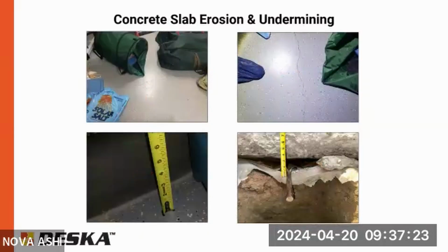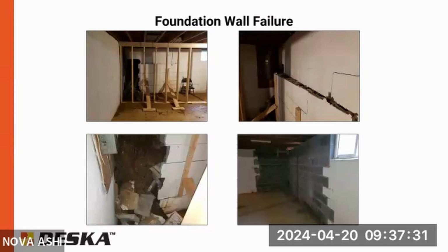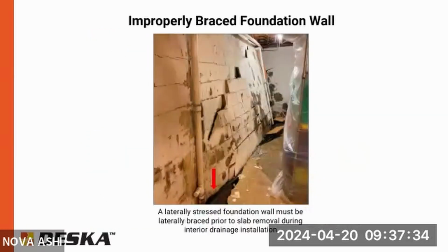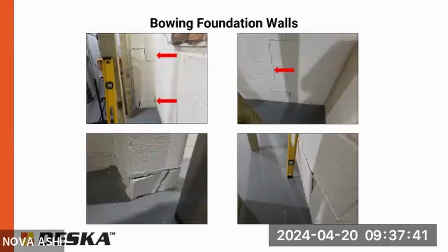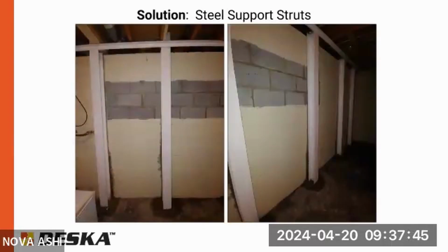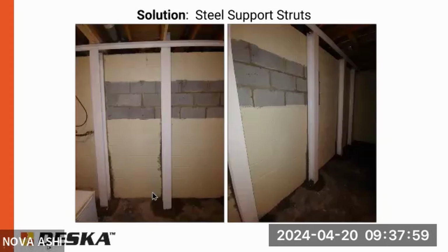Also in a basement, if you look closely at a block wall, usually the bottom row of blocks, you won't be able to see a full block here. Usually you'll see a half of a block or a couple inches or 1 inch. And that would tell you that the wall keeps going down into the ground to a footing ideally. Now, if you see a full block, then there's a chance that the wall may actually be sitting on top of the slab, in which case the slab could be structural.